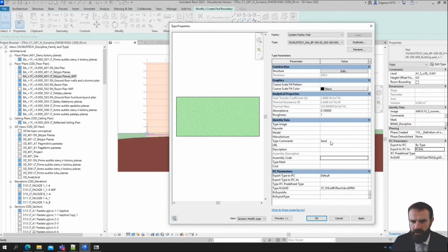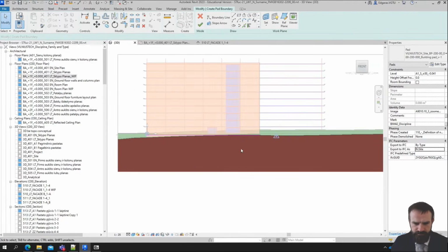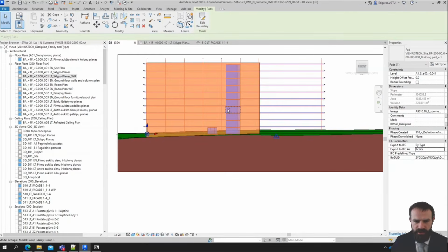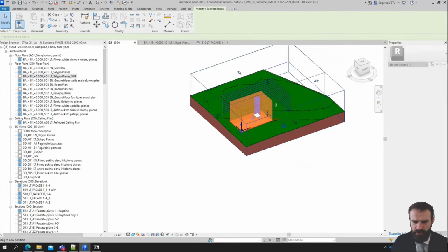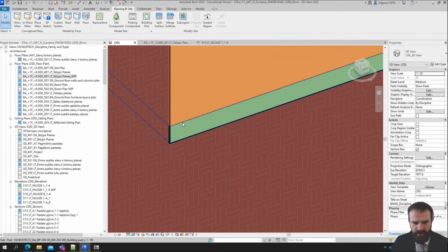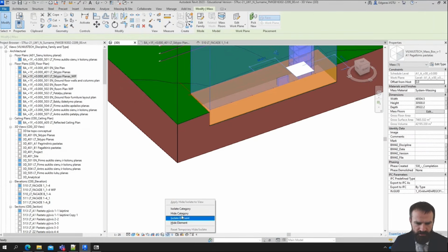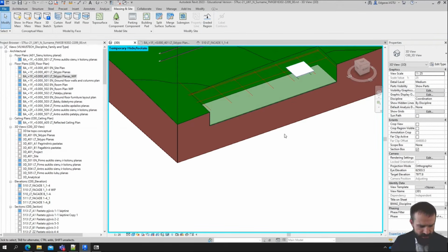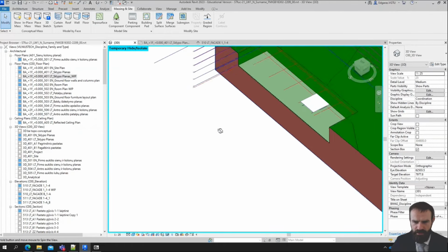Later, I can finish it up. Okay, so I click apply. Okay, click OK. And now all the parameters are filled up. I can click finish. And now I will change the location of my section. And now I can see this nice sand object is created here. And if I hide mass category, hide category, so in my building area, I have a nice excavation for my building.